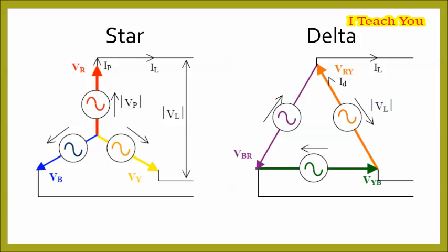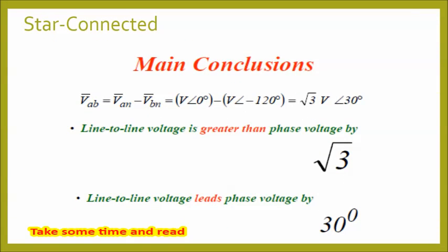In three-phase systems, there are mainly two configurations: number 1, star or Y, and number 2, delta or mesh. In star configuration, there is a neutral wire along with the three phase wires. But in delta, we meet only three phase wires and no neutral. We are used to considering the phase which has the angle of 0 as the reference.